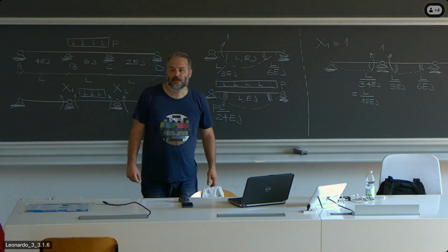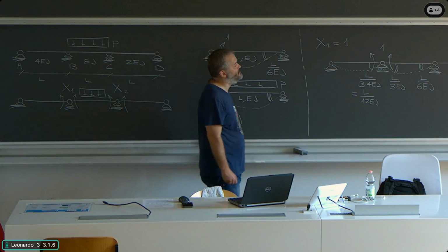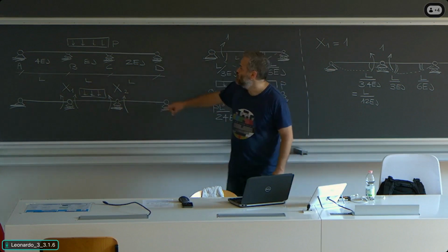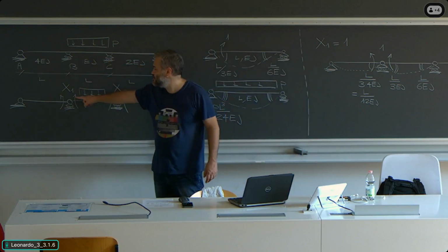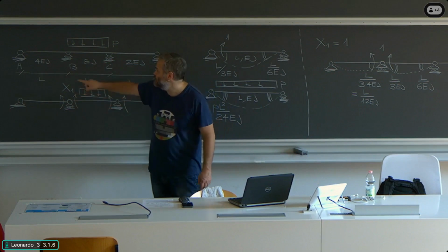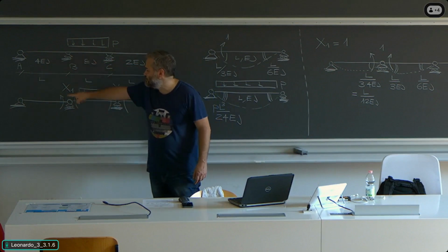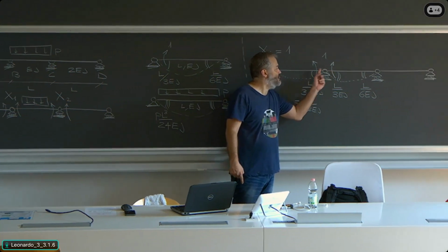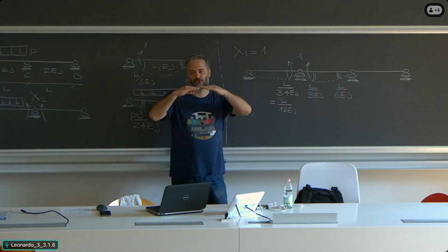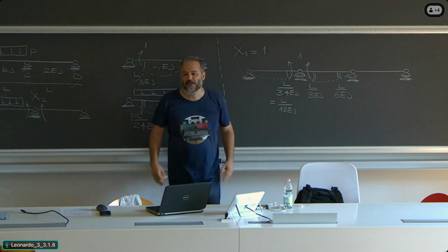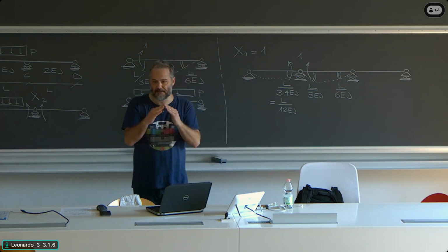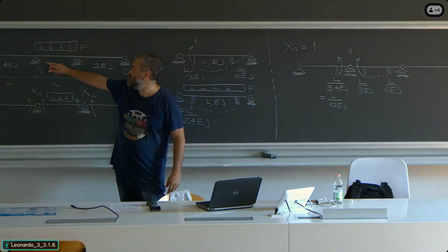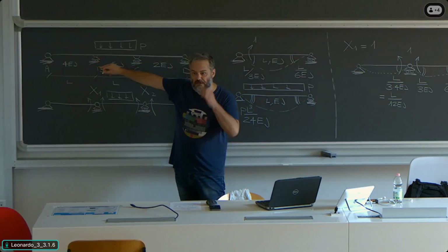Now you see clearly what I mentioned and what I anticipated. What does it imply to highlight these two bending moments here and to move from this structure to this? As you see here, there is a relative rotation between the two spans like this. I call it a kink in the beam, which cannot take place in the structure we started from because there is continuity.